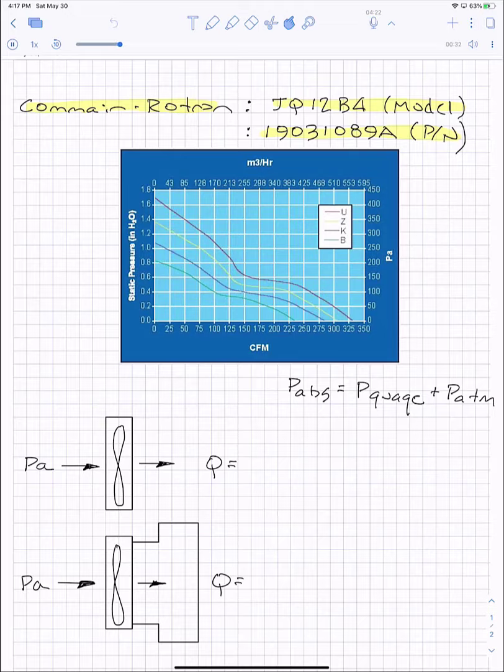Mouser, and the designation on the model number, this B, tells us that we've got this fan curve we're going to be using here, and that fan curve follows this green line here, and I'll trace over here. And so depending on the operating conditions of the fan, we'll be at some point on that fan curve.